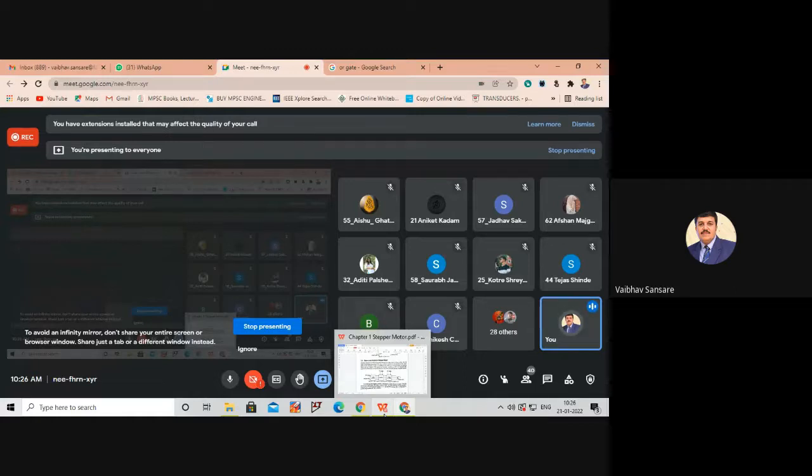Whereas in case of closed loop control, the position of the rotor is sensed by position sensing devices or position sensing elements, and this position is fed back to the input commands, that is, given as feedback to the input system. Actually, that input system is the digital comparator and translator circuitry. So the actual position of the rotor is sensed by the position sensor, and the appropriate command is given to the input side translator and digital comparator. Actually, that position sensing element is called the discriminator.